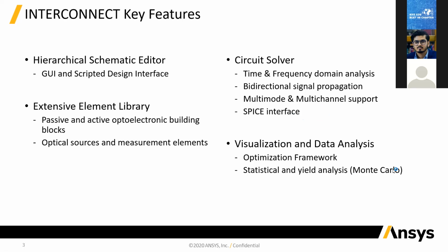In terms of visualization and data analysis, it has an optimization workflow similar to the component level tools. So you can optimize your circuit using that or run parameter sweep. And then on top of that, it can perform statistical analysis like Monte Carlo sweeps.